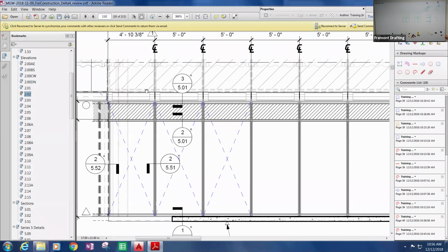So that joint might become 1 or 1 1/4, but because the architect can't see it from the face in this direction, he's seeing a nice little small 1/2 inch joint. When we apply that angle to the mullion, he's less concerned with that joint getting larger to take that movement from the side. So it'll be referred to as a slide-by condition. You may hear it referred to that. That's what precast calls it. Slide-by, yes. That's how precast refers to it.